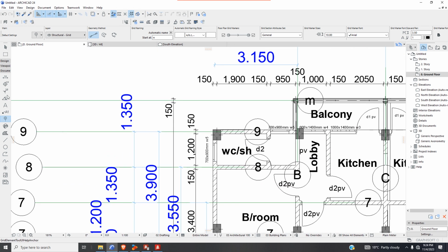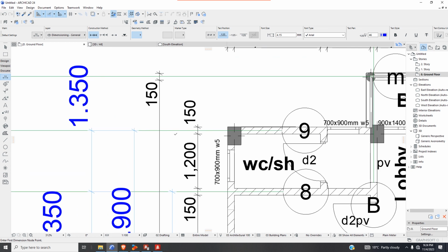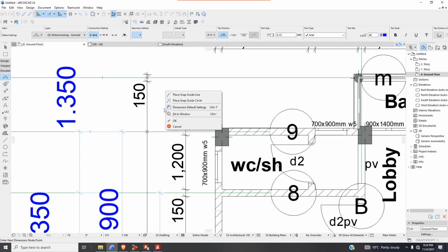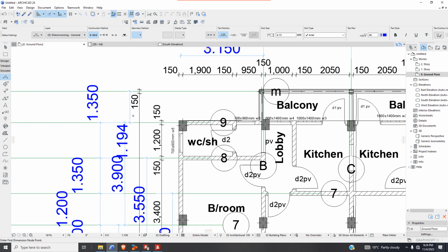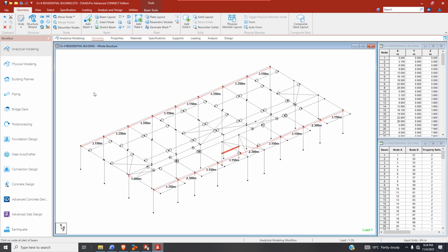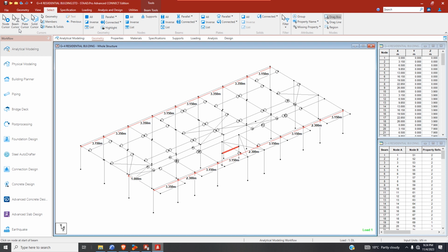Because this building was not designed for seismic loads, likely we use wind loads: W X, W L Z. I'm going to add that load. Add self-weight, add, assign to view, assign yes.